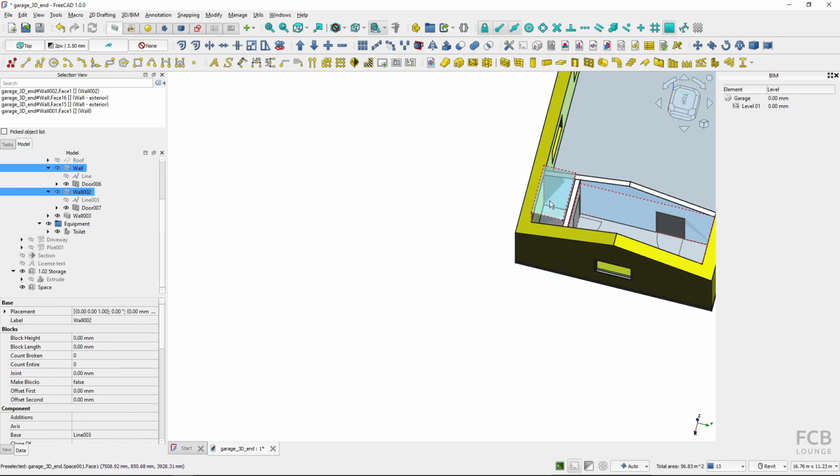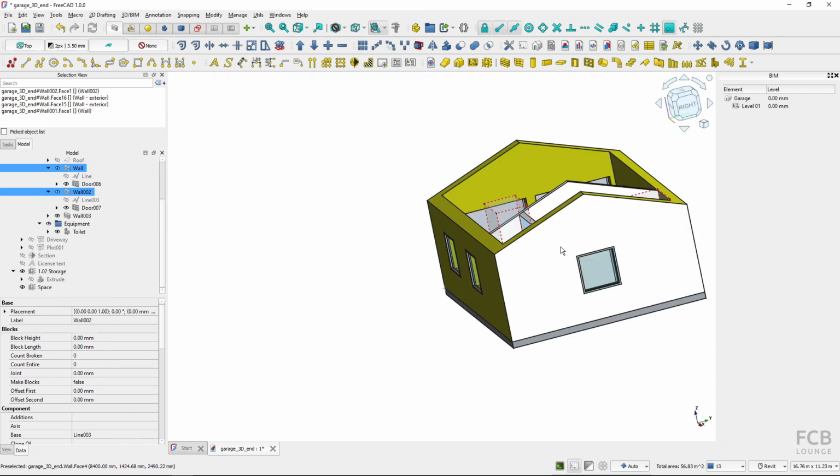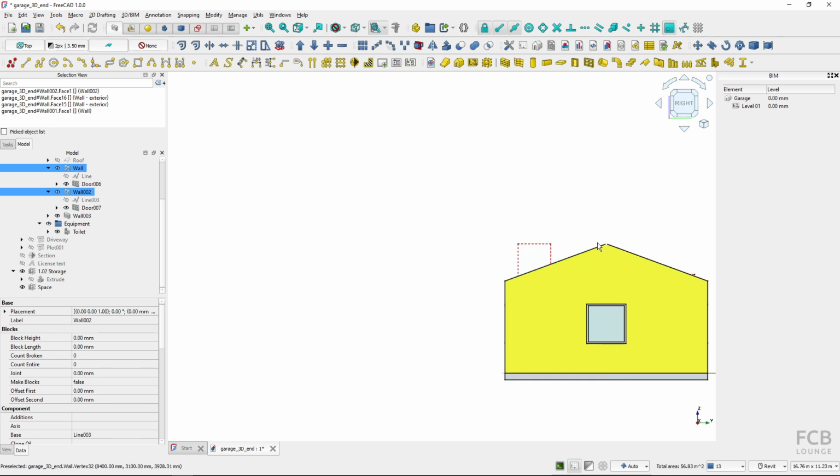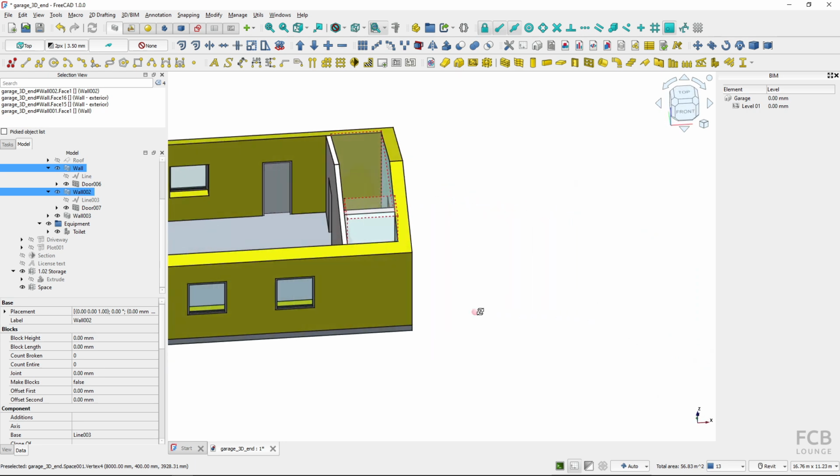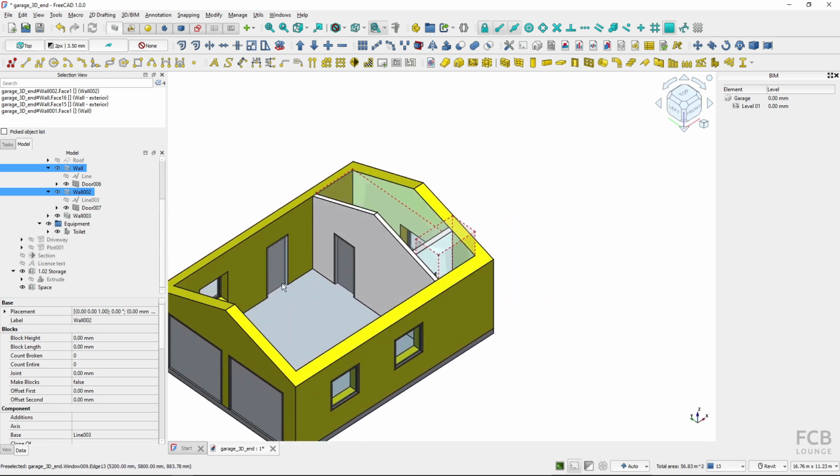So it was created based off those selected faces, and the height is the highest point of any of those faces. So it was this one, so the height is like this. This is not correct height for us, of course, but I will show you when I will be creating space for the parking space, how to make the size of the space compliant with the slope of the roof.